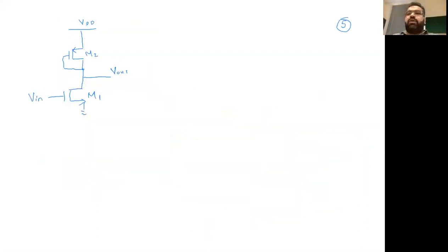Let's first draw, just again for simplification. You don't have to all the time draw all the capacitance. If you can short some capacitance, you are free to do that. But what I'm doing, I'm just drawing all the capacitance first, and then we can move forward. So for simplification, I will just redraw this thing. We'll give some space so I can redraw all the capacitance. So one MOS ultimately has 4 parasitic capacitance, which we normally assume.